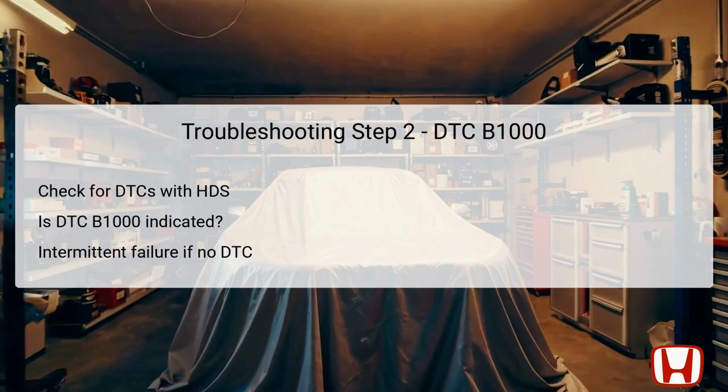process. After performing the initial steps, the next action is to check for DTCs again with the HDS. It is essential to confirm if DTC B1000 is still indicated after following the reset procedure. If it is indicated, proceed to further diagnosis. Conversely, if DTC B1000 is not present, this could imply an intermittent failure of the communication bus line, suggesting that the wiring or connections are likely functional at this time. In such cases, technicians should inspect for potential loose or corroded connections.